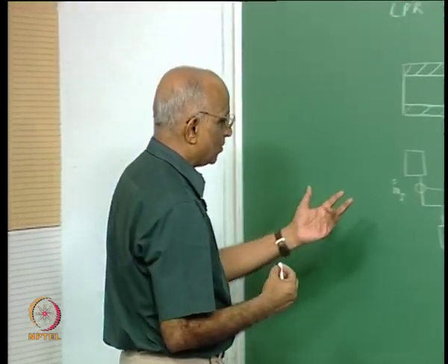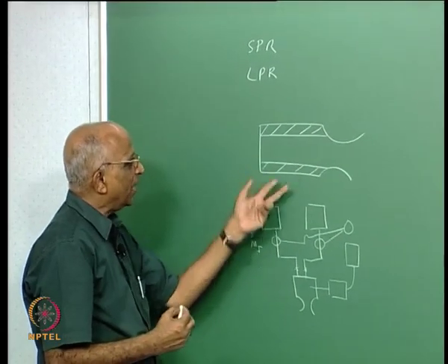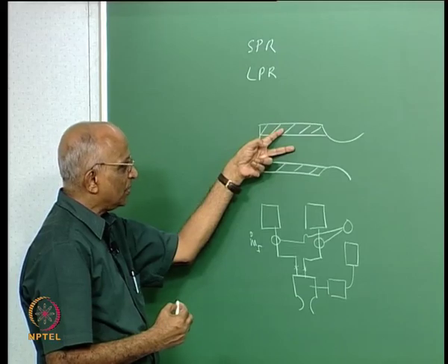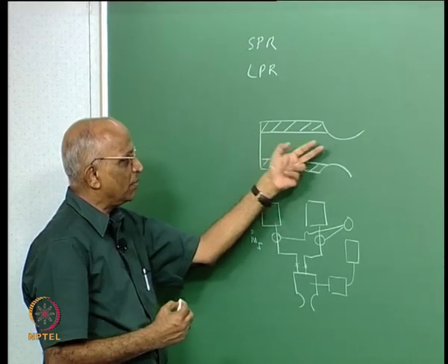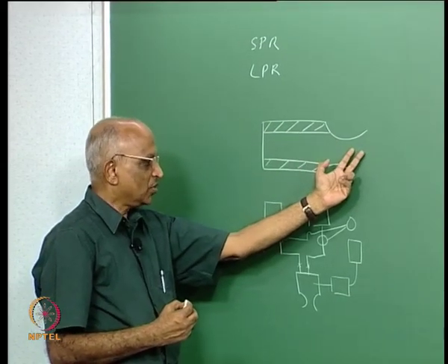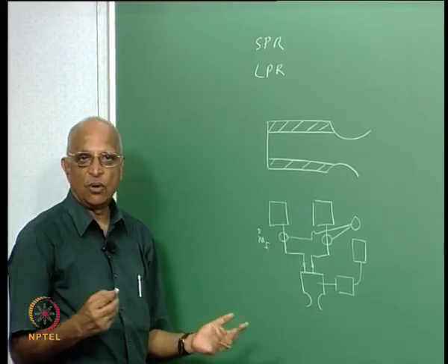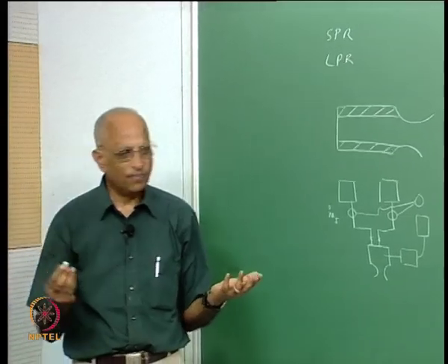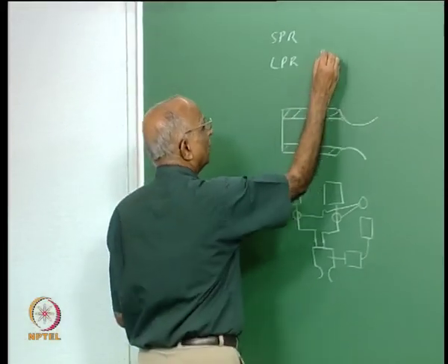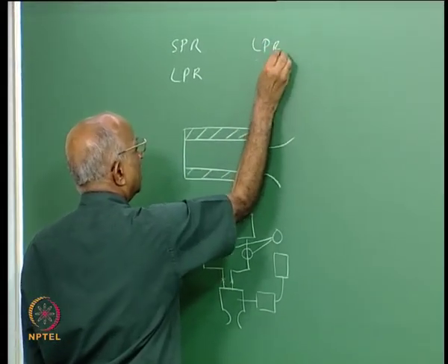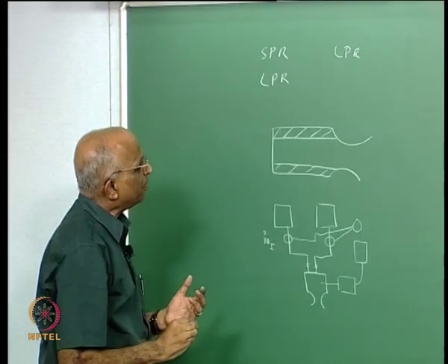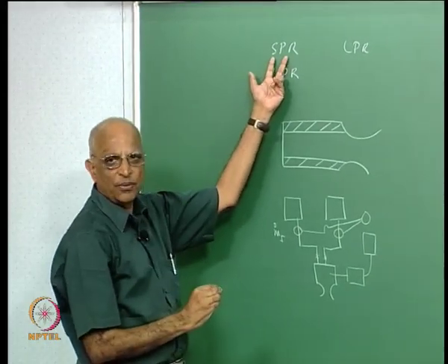Not only is it more versatile, it also has higher performance compared to solids, because in solids we add aluminum, the molecular mass of the exhaust is high, whereas here if I choose hydrogen oxygen, my performance, or my specific impulse, is quite large. Therefore, we can say in general the liquid propellant rocket is more versatile, has better performance than solid propellant rockets.